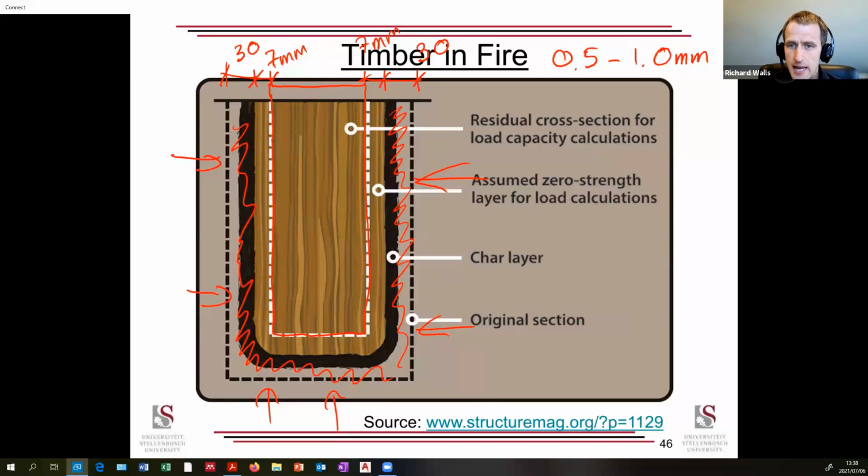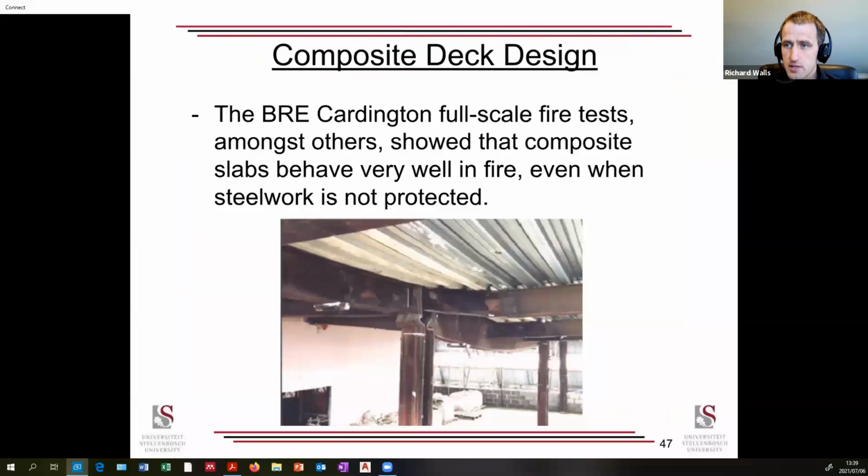The biggest challenge with this is now the timber is contributing to the fire load. So you used to, for instance, have a 60-minute fire rating, but now your timber skeleton contributes to the fuel load. So maybe now is 60 minutes enough? So you may need to increase the fire resistance that's required, or what's often specified in some of the codes, you limit the area of exposed timber, so you limit the area of contributing fuel to the fire load. So there are ways and means of dealing with it, but timber is a growing material.